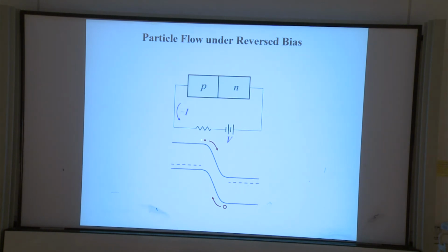Electrons will go from the p side to the n side, so going right, and holes will go left. Since they are minority carriers, not the majority carrier in the respective type of semiconductor, the amount will be very low, hardly any. So the drift current is very low, with hardly any conduction in the reverse bias condition.